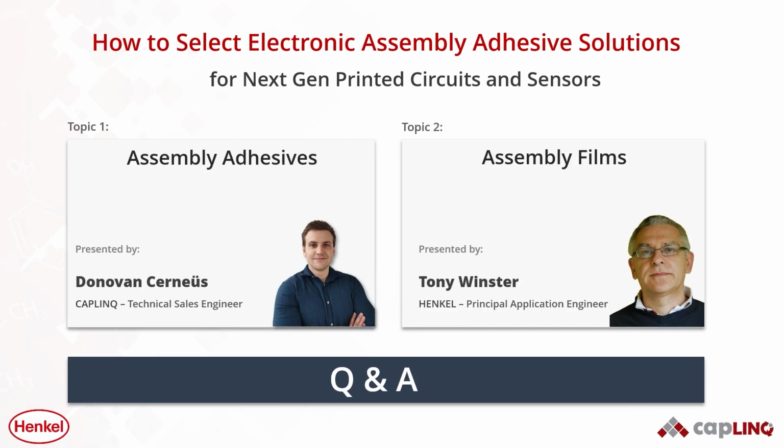I can say a few words about it. Actually, it's not nickel. Usually we use gold-plated nickel to give it some stability with time. But nickel is quite good because it's hard. Gold is soft and it just squashes. So it's good to make the particles out of a fairly hard material, and you can push the components down and make a good contact without distorting and flattening out the small particles. Okay, thank you very much, Tony. I hope that answered your question.